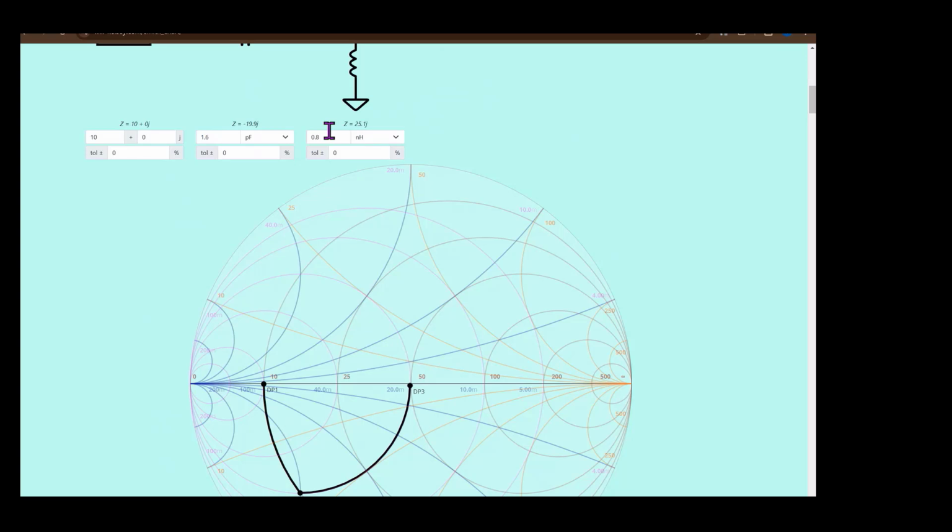This is why we like to use Smith charts. I could have hand calculated that. We did an L match the other day. An L match, even when you're good at hand calculating them, takes a few minutes. You can of course write a MATLAB routine that'll do it for you if you want to. On Wednesday, I'll set up an S parameter simulation. I do have a demonstration of doing an S parameter simulation in Cadence online and using the normal flow.